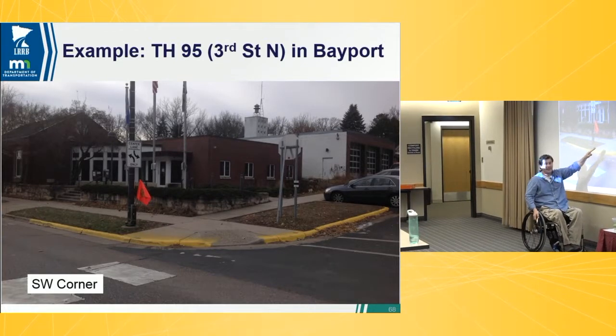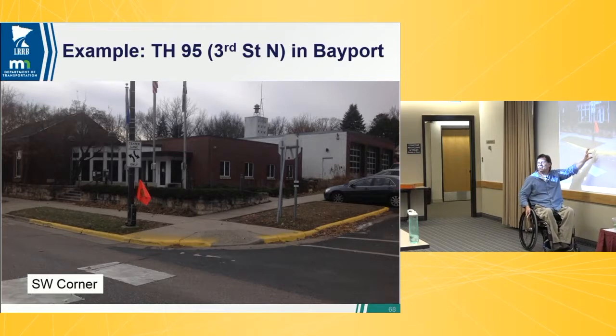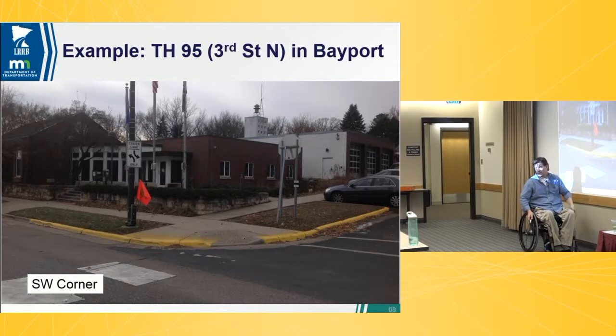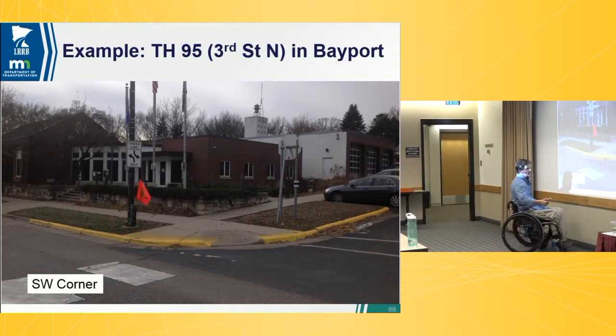So again, I got to put a landing in, so that hurts. But I've also got a 6-inch curb to make up. So if I can't change that top elevation, I got to change this bottom elevation. And all I can do is start doing stuff with the road. So that's what I'm going to start doing here. See where I can start, make that tie-in begin.